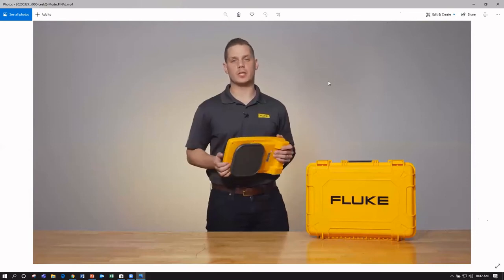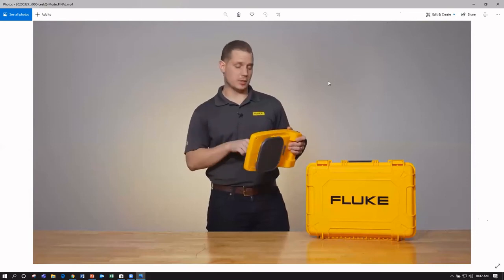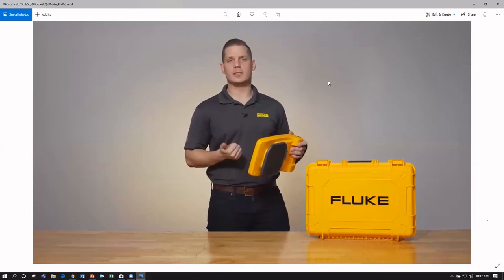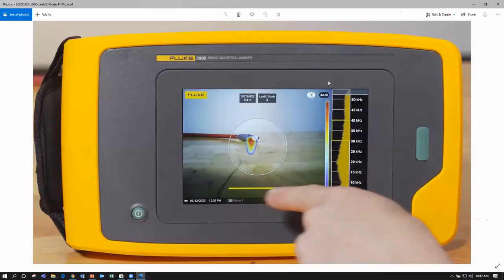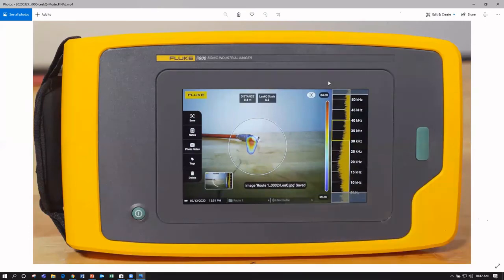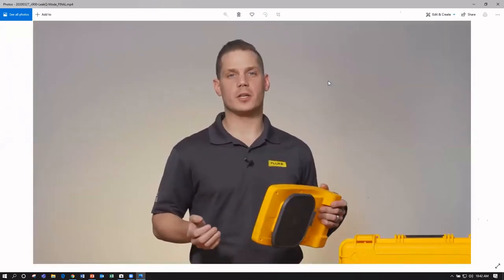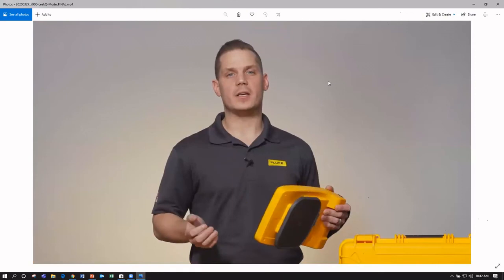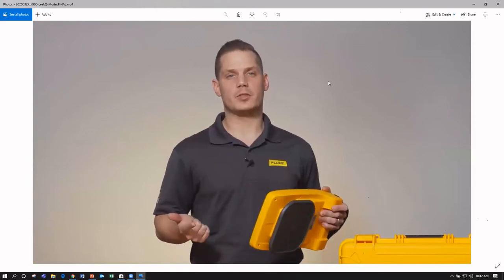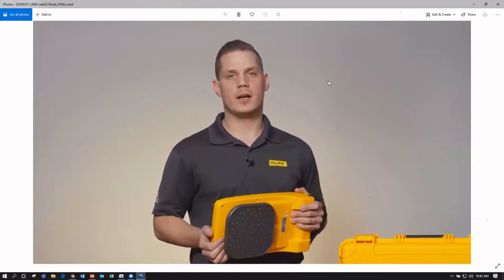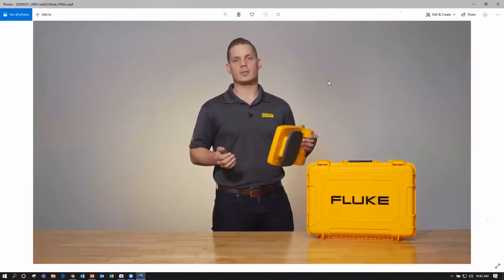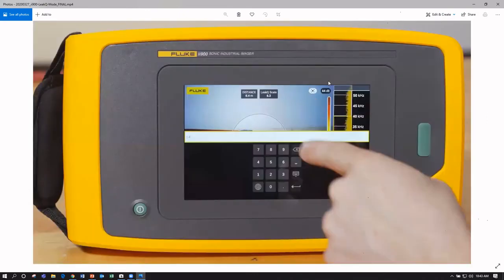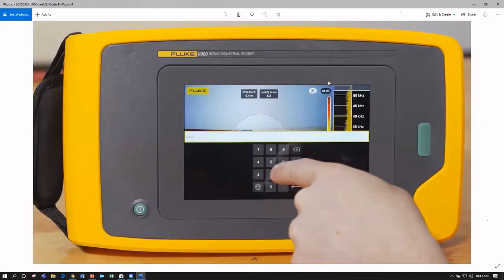Capturing images in LeakQ mode is a little bit different than capturing images in the image mode or video mode with the ii900. Once you've got the leak positioned in the center of the screen and you've got both the distance and the LeakQ severity scale populated, you're gonna wanna push and hold the green button and hold the camera fixed on that leak for 1.5 seconds. If you have a leak positioned in the center of the circle, but you're not seeing a distance value, it might be because you're too far away, the environment is too noisy, or you don't have direct line of sight. But you can still get a leak quantified value estimation by manually entering in that distance. All you have to do is push that distance icon and manually enter the value.